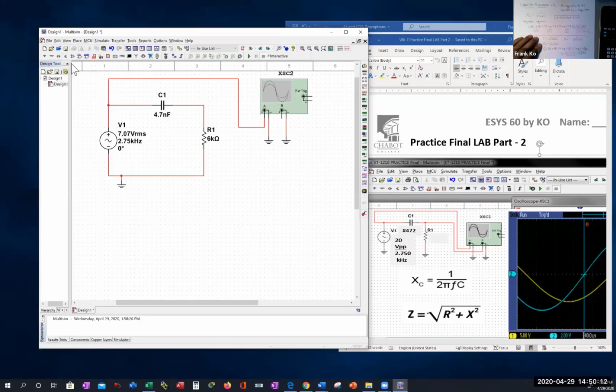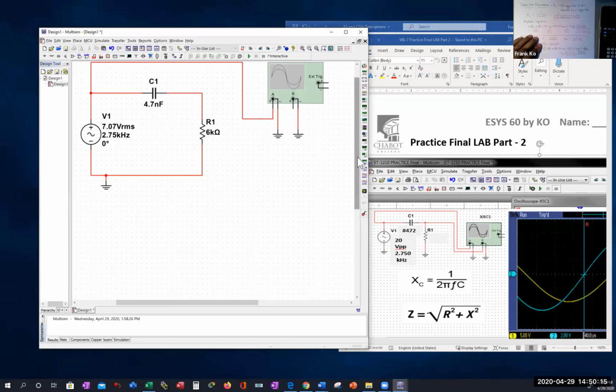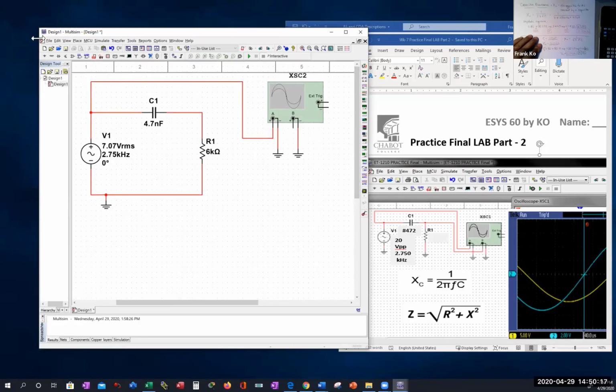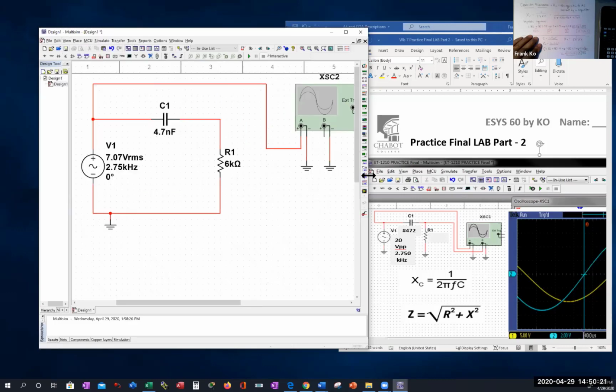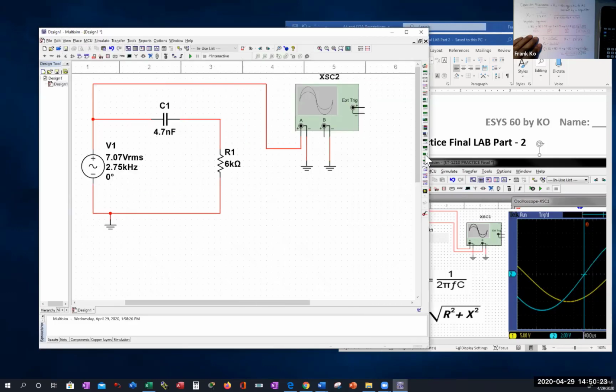So let me go ahead and view again. Let me zoom in again, and let me zoom one more time since I have all kinds of space to do this with. This is nice. Zoom in. All right, I click on the channel B wire, bring it over to here, click, come up to here, follow the grid lines, click, and come over, make a connection here and click. Great.